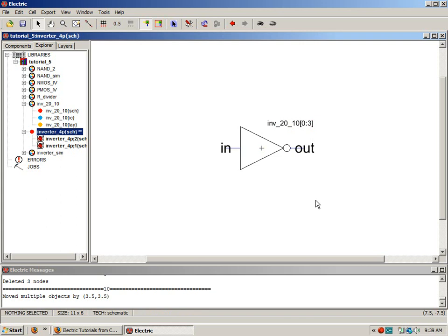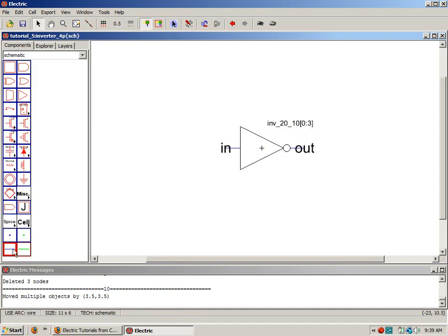So these schematics, all 3 schematics are exactly the same. So we need to connect wires to this icon. So if I go here, let's make sure we have a wire arc. I go here and I put a wire arc there. It connects all 4 inputs together. And that may be what you want, but in some cases it's not. So instead of doing that, let's go back, select the bus arc, and pull it out like this.